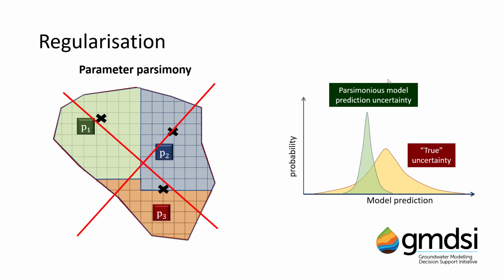Having many parameters does come at a cost. When using derivative-based methods, such as are implemented in PEST and in PEST++ GLM, the computational cost of calibration is proportional to the number of adjustable parameters. Operation of these methods requires carrying out a model run for every adjustable parameter during each iteration of the inversion process. Thus, available computational resources place a hard limit on the practical amount of parameters that we can include.